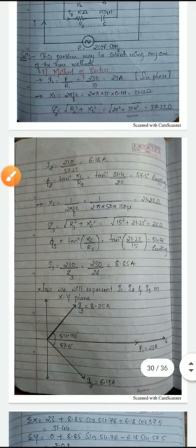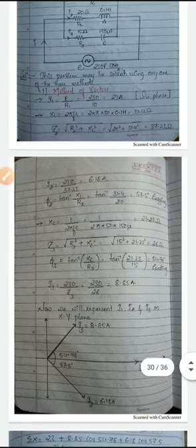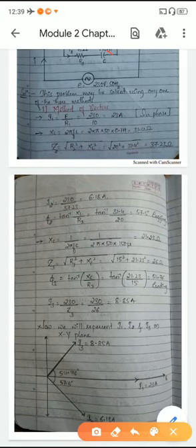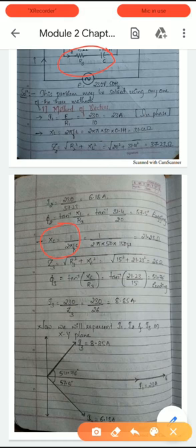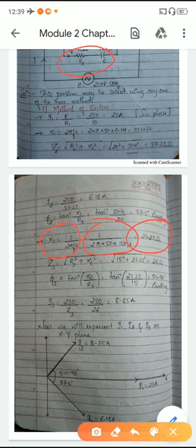Next we will go for the third branch, which consists of a resistor and a capacitor, right? As it is a capacitor, our job is to calculate the value of Xc. Xc is equal to 1 divided by omega C, which is nothing but 1 divided by 2 pi f into C. Therefore we are going to get Xc as 21.23 ohms.